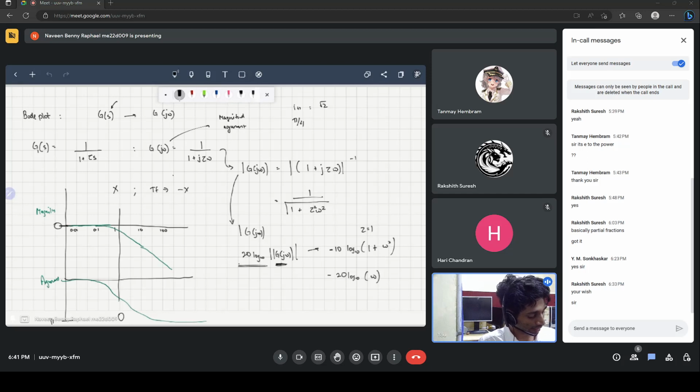Therefore we can use the x-intercept of the magnitude and the point where the argument becomes 0 as very important points, and we always draw vertical lines from those points to see where it intersects the other plot.